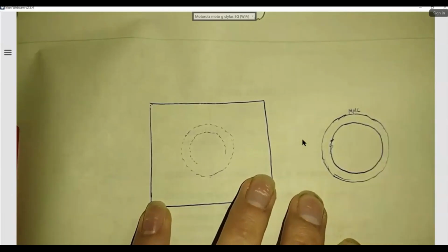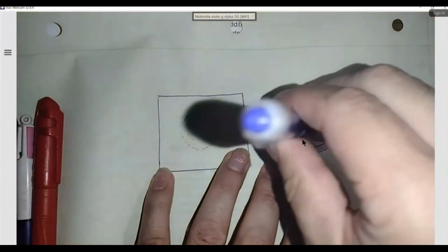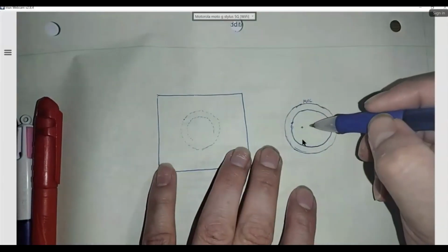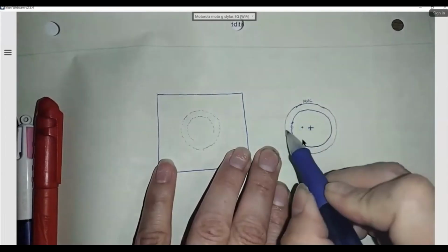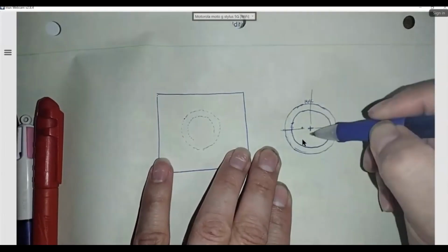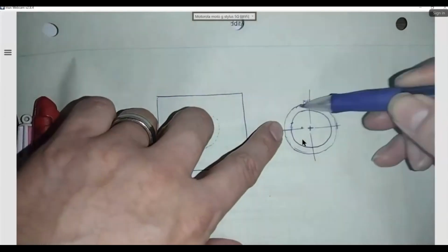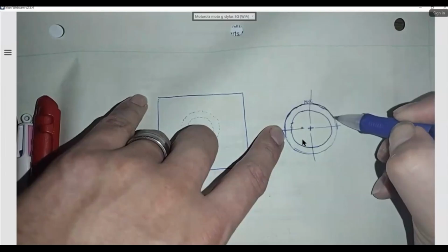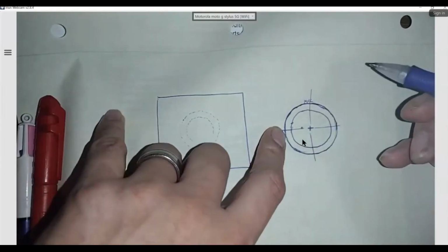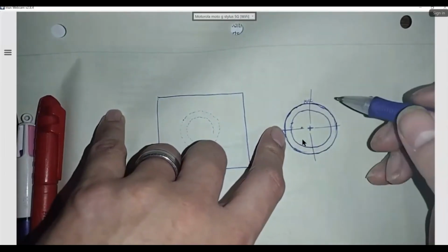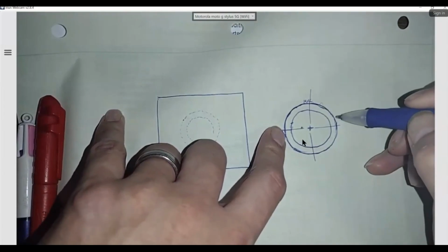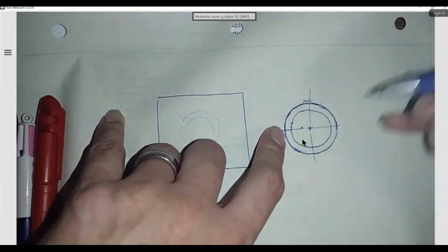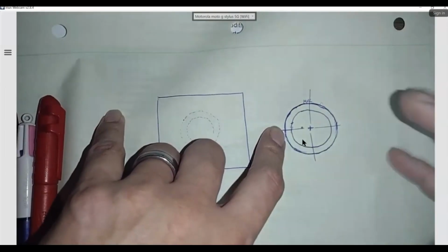Now I just told you that my axis can shift sideways, up and down, left and right. Yes? So I am going to want to assume that this is my bullseye. This is where the perfect condition is. This is where my part is at the MMC, which is the biggest I can get. At this point of time, when it's the biggest, it cannot have any form variation, because if it has a little bit of crookedness, it is going to get off my upper limit. And if it gets off my upper limit, then I fail. I lose the D. Remember, GD&T, so the D is gone.